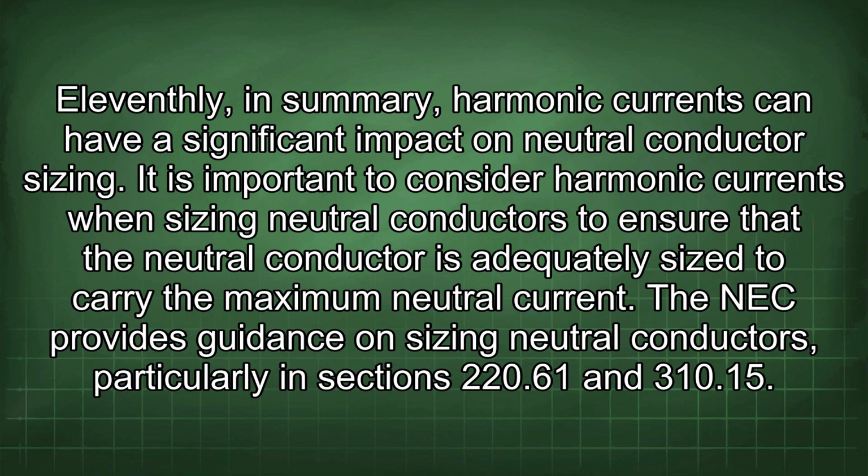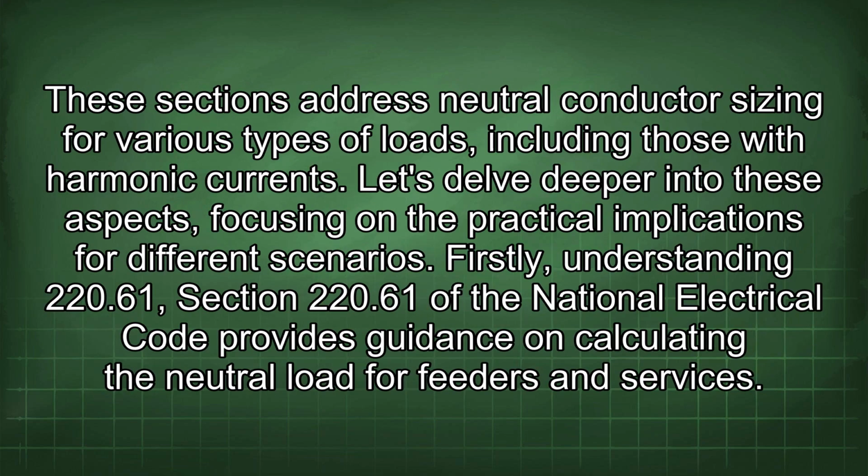11thly, in summary, harmonic currents can have a significant impact on neutral conductor sizing. It is important to consider harmonic currents when sizing neutral conductors to ensure that the neutral conductor is adequately sized to carry the maximum neutral current. The NEC provides guidance on sizing neutral conductors, particularly in sections 220.61 and 310.15. These sections address neutral conductor sizing for various types of load, including those with harmonic currents. Let's delve deeper into these aspects, focusing on the practical implications for different scenarios.